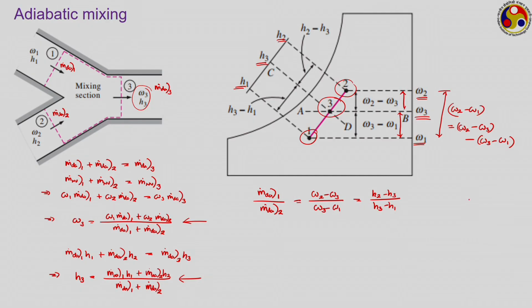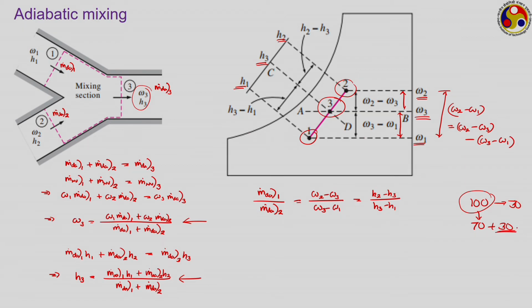And it is very much possible, like suppose if we are taking say 100 units of air back from the room via the exhaust, maybe only 30 units of that goes to the surrounding, the remaining 70 units comes in and that gets mixed with 30 units of fresh conditioned air, and subsequently the entire 100 units of this mixture comes back to the room. So, if we are rejecting or exhausting the entire 100 units of air, then your air conditioner has to condition again 100 units of air. But in this situation, because of the mixing, we just have to condition only 30 units of this.